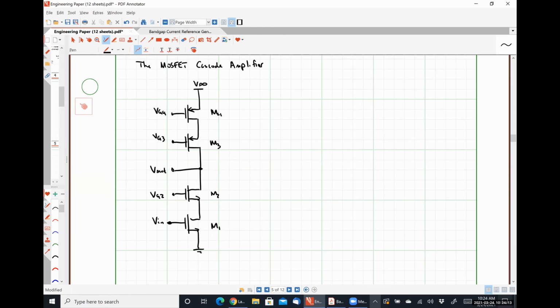So effectively the exact same thing, except we were realizing all of our NPNs with NMOSs, all of our PNPs with PMOSs. If we were to look at the small signal analysis of this guy, what would be the only fundamental difference between what we had with the BJT circuit? We'd have open circuits wherever we saw R pi. So from that, our short circuit transconductance would be GM1,